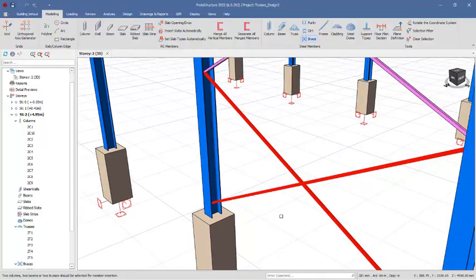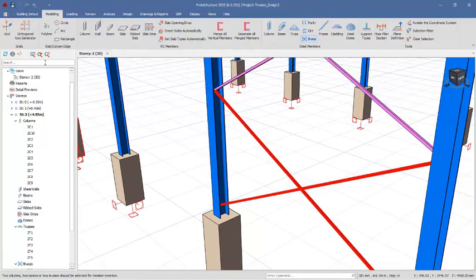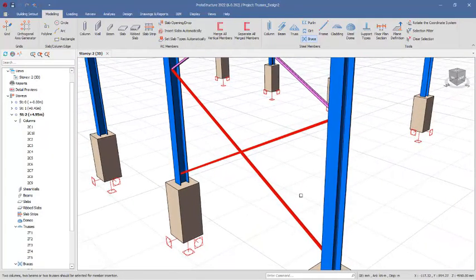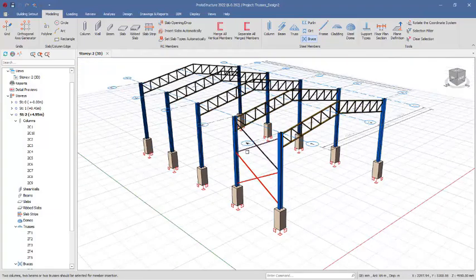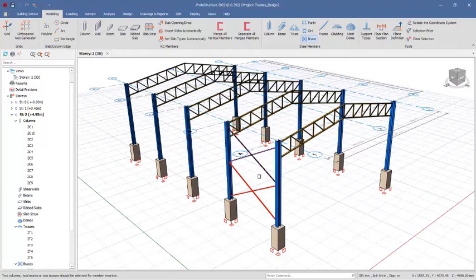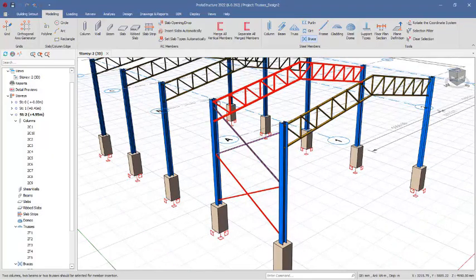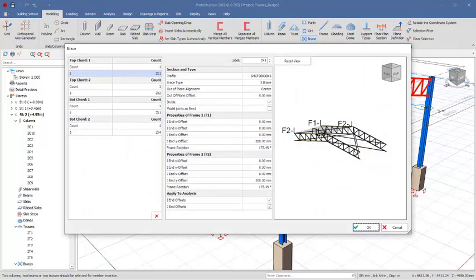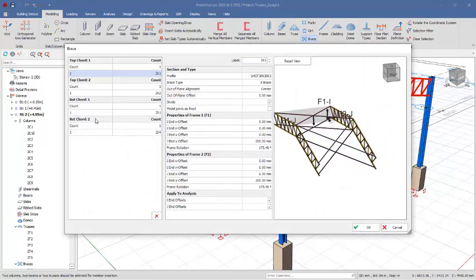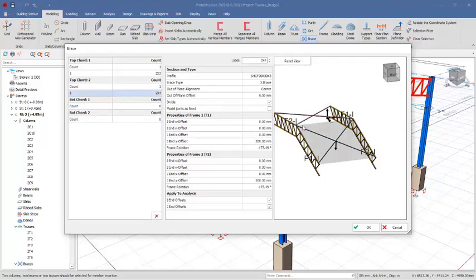So this same thing we are going to be using for every other provision. We actually have braces for the roof as well; the same thing will be applicable. Select the first truss and the second one to have this. So you can see it done right there. What you just need to do for the bottom count is make it 0 right there. So come to this bottom count as well and make it 0. So we are not having this.